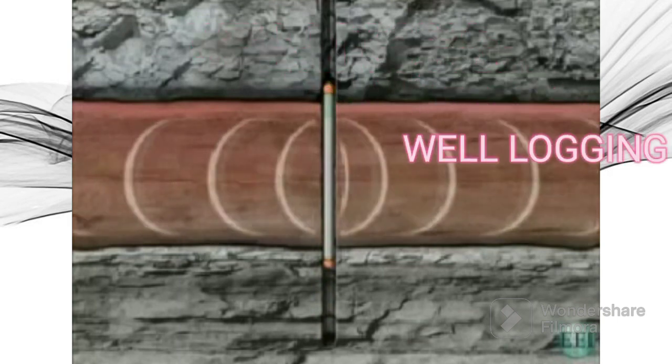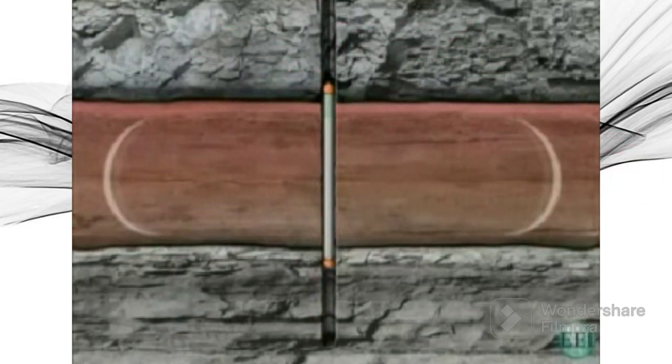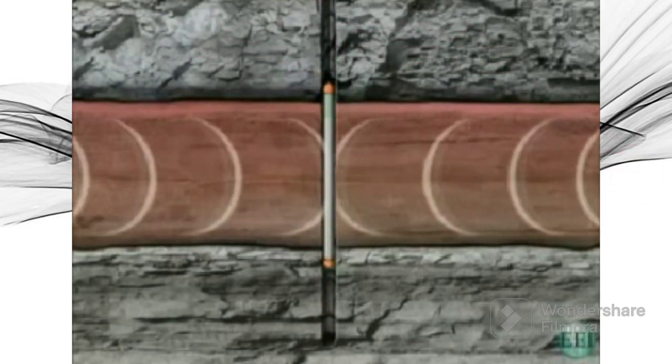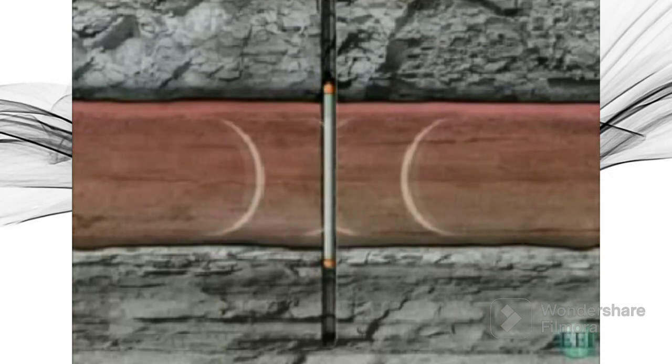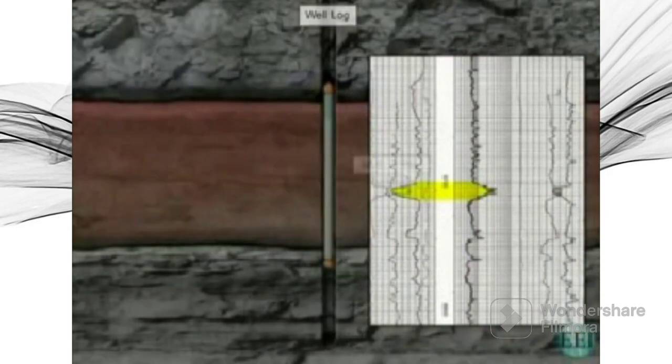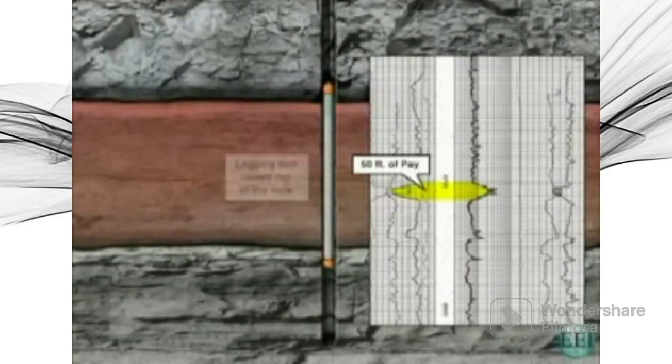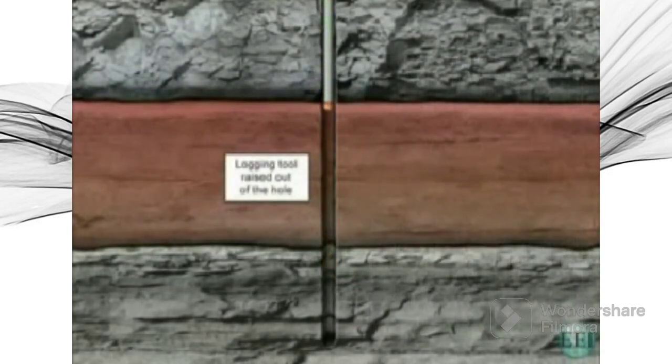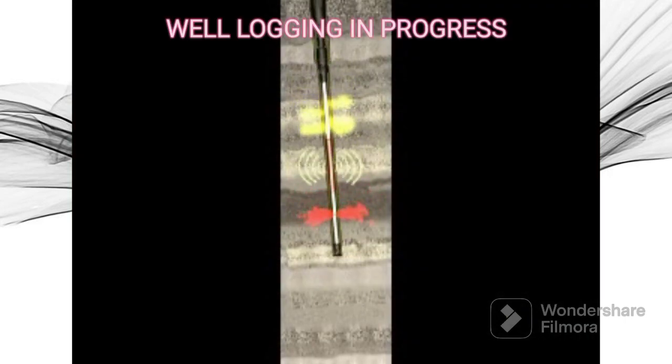Well logging is the process of measuring and recording characteristics of the well. The logging information lets the oil company determine if the well indeed can produce oil or gas. At this point, the company will decide whether the well is to be completed or plugged and abandoned. If the well is designated as a producer, the crew inserts the pipe back into the hole to ensure that the hole is still intact and circulates mud fluid.